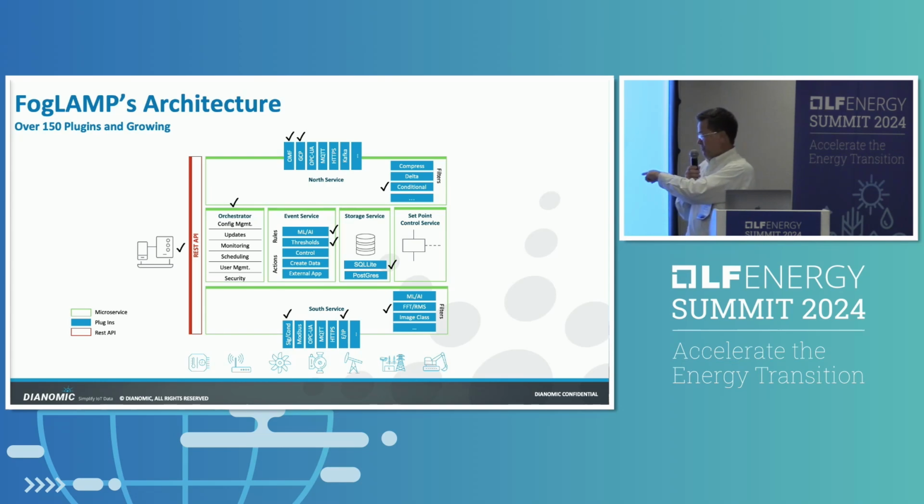So, I might have no security on Modbus, I might have a new DNP3 using a certificate, and then up north I might be using a token to send it to my historian, but I might be using this root of trust to send it to the cloud. So how do I manage 4 different security parameters on really what essentially is one data pipeline? And that's actually what FogLamp Manage does very well. But it's all REST, so it's all HTTPS between microservices.